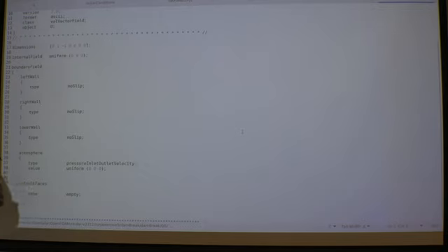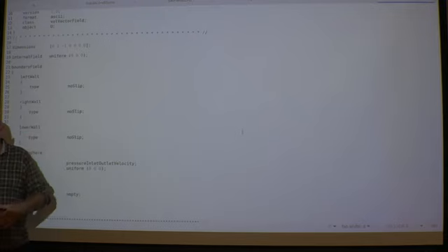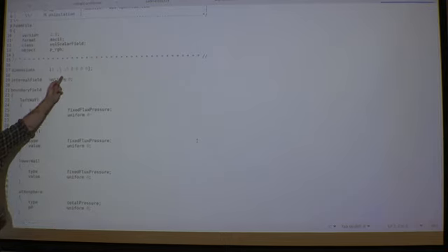For the other files, the velocity, well, here's a standard. You have just a solid wall, no slip there. And then the atmosphere, where we have a special pressure inlet-outlet velocity. So it's fairly open. It can go either in or out. If it comes in, then we don't give it an initial velocity. And for the pressure, let's have a look. Here we go. Look at the dimension. This is Pascal, not pressure divided by density. Be aware of that one. And then we just say 0 all over the place, and we have a fixed flux pressure, as they call it. We could have used zero gradient as well, should be possible. And then at the atmosphere, there we have a total pressure, 0. Fairly easy.